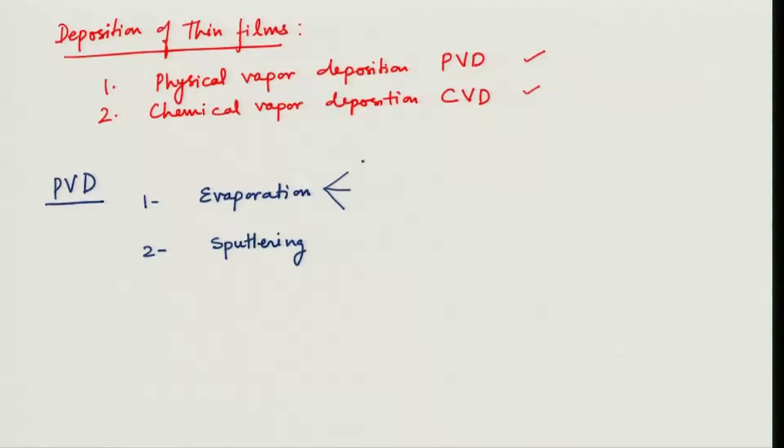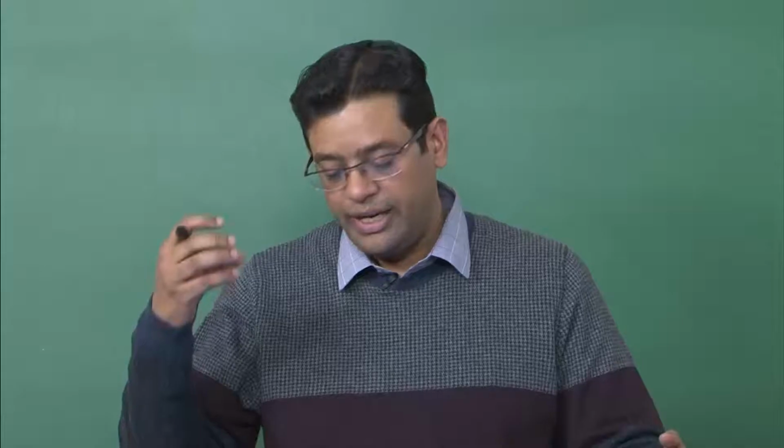where they will get deposited and make the thin film. The way you can do this is either you can heat them using thermal energy. We will also discuss E-beam heating or electron beam deposition, or you can also do pulse laser deposition, in which you use pulses of laser to heat the system or heat your source. So, this is by heating.